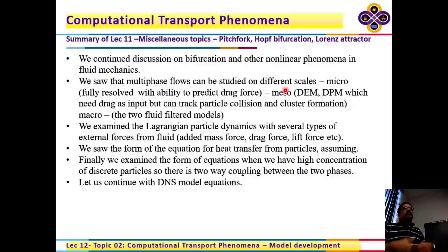These forces are the drag force and the lift force. We talked about the origin of these forces. It's essentially a purely hydrodynamical interaction between the dispersed phase and the continuous phase, often studied for a single particle, and then the expression is applied to multi-particle systems in an ad hoc extension.